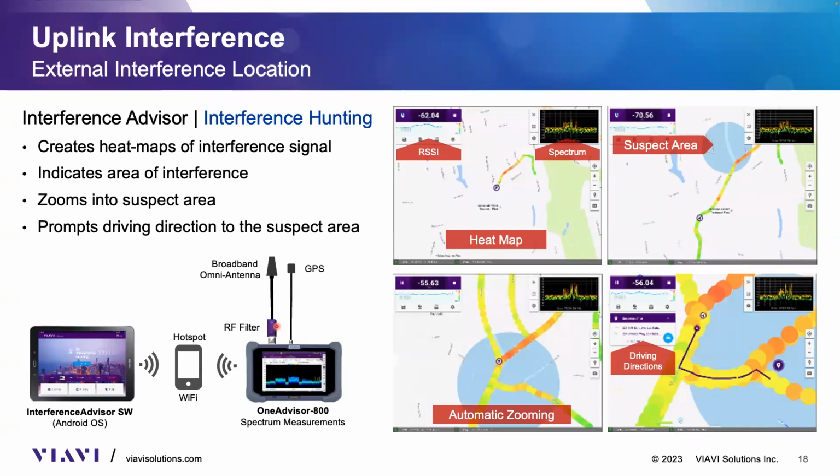Typically they might have a rejection of 30 dBs, meaning that everything that is outside of that band is going to be attenuated by 30 dBs. But yeah, we have different filters based on the uplink frequency band of interest. Certainly we need to pick the right filter, the one that we're going to be using for the uplink that we're testing on.